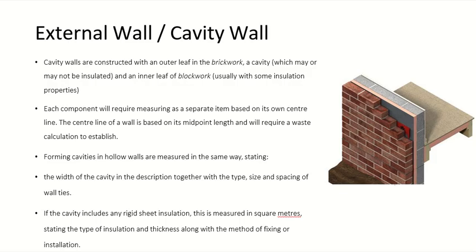Okay, so the contractor may charge you for forming the cavity as well. Although it is called a cavity, which means nothing, the contractor may charge you because practically you cannot keep it completely empty. So he will charge you, and you have to calculate the quantity of the material you are going to use in the cavity.